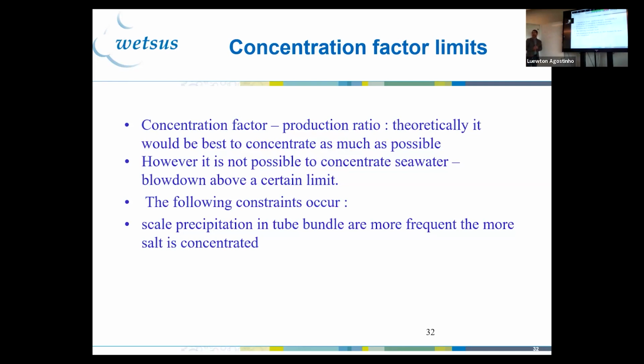But what is the problem with desalination technologies if you do this? If you increase this ratio compared to that one, it means, because the concentration that you get from the sea is the concentration you get from the sea, and normally, I repeat myself, this is the 35 grams per liter, right? So if you do this balance, and you increase the total water production in detriment of what you produce of your brine, it means that you're going to have low volumes of brine that you discharge to the sea. But this will be highly concentrated, really, really.